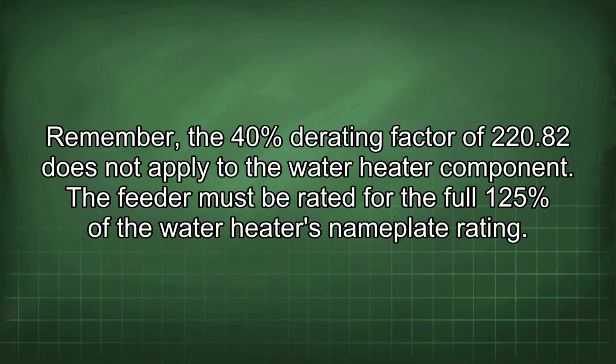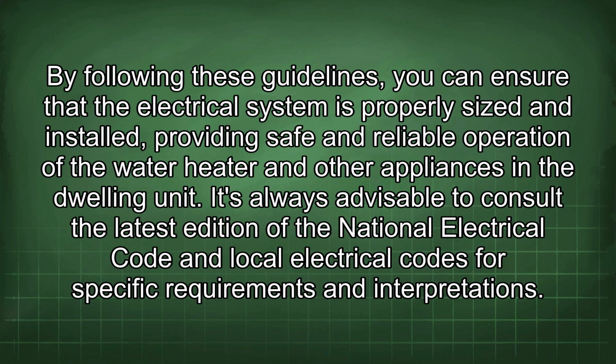Remember, the 40% derating factor of 220.82 does not apply to the water heater component. The feeder must be rated for the full 125% of the water heater's nameplate rating. By following these guidelines, you can ensure that the electrical system is properly sized and installed, providing safe and reliable operation of the water heater and other appliances in the dwelling unit.